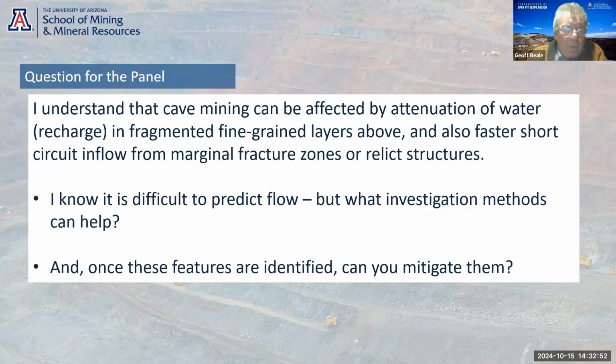So you're right, it's very difficult to predict flow. It's very difficult to determine which structures are going to convey water. But a good cave operation will monitor the free water, the moisture content, and the fine grained material of all its draw points.